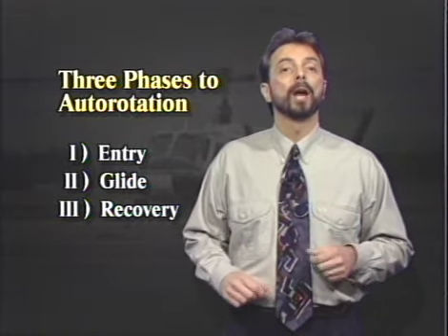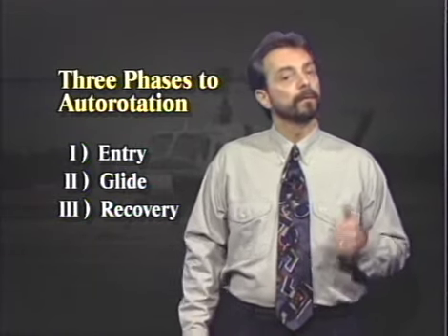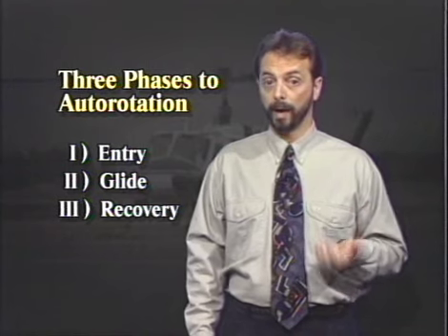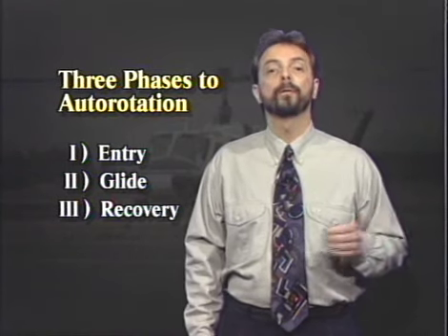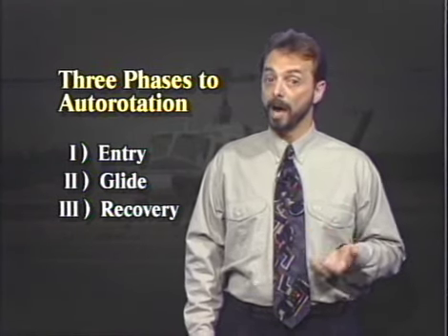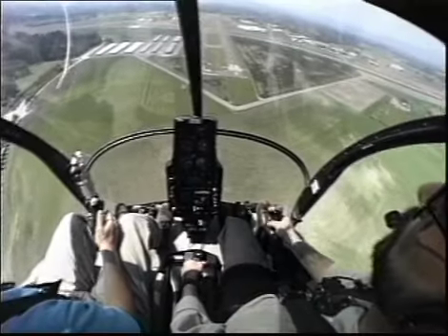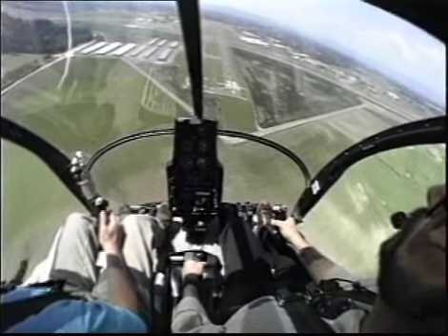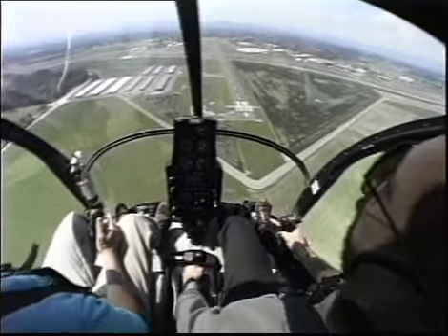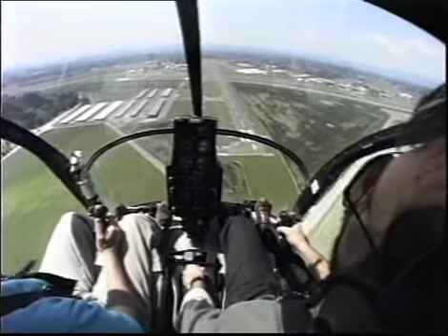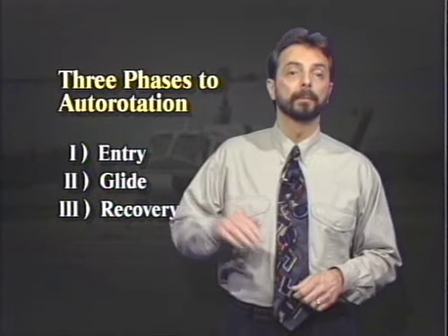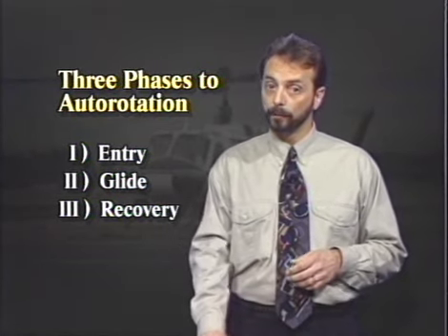The entry phase is perhaps the most important. If the entry to an auto-rotation is performed correctly and smoothly, the subsequent phases become much easier. If not, you may find yourself playing catch-up the whole rest of the way down. The first step in the entry phase is to lower the collective pitch control immediately and fully to maintain rotor RPM. Lowering the blade pitch converts the usual downward flow of air